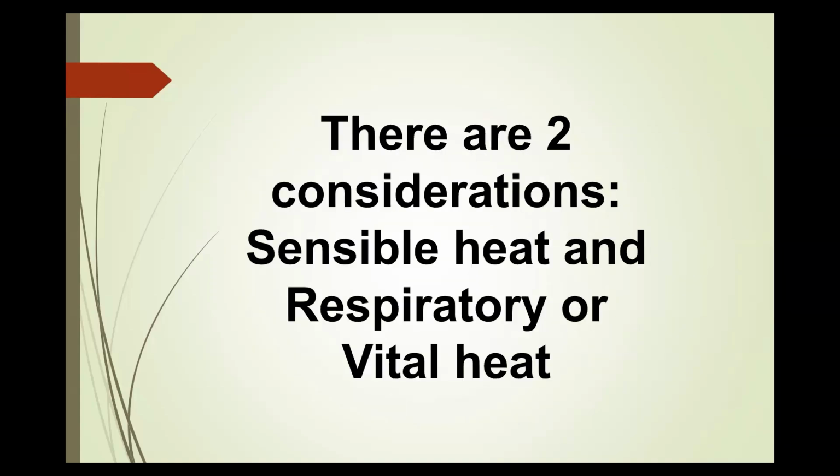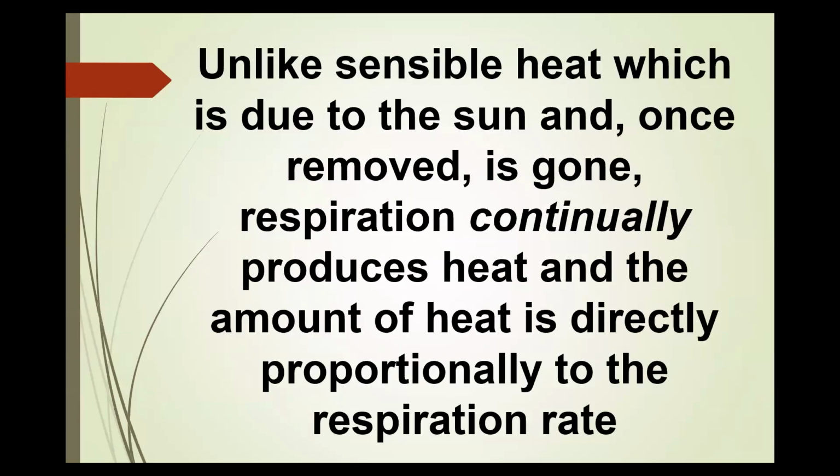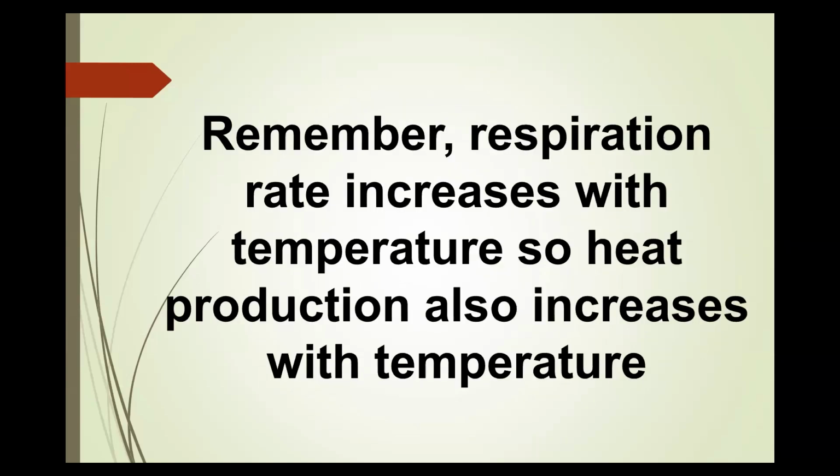There are two considerations: sensible heat and respiratory or vital heat. Unlike sensible heat, which is due to the sun and once removed is gone, respiration continually produces heat, and the amount of heat is directly proportional to the respiration rate. Remember, respiration rate increases with temperature, so respiratory heat production also increases with temperature.